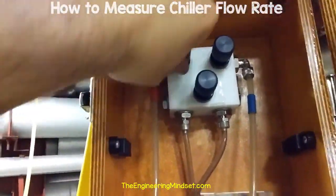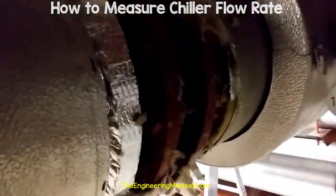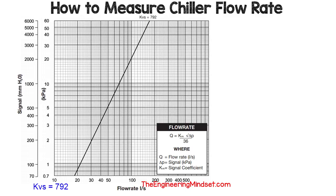So to do this, just open up the bypass valve and close the high and low pressure valves within the manometer. After that, you can then close the high pressure valve on the orifice meter and disconnect the hose. Then after that, do exactly the same on the low pressure side of the orifice plate. So now we can calculate the flow rate.